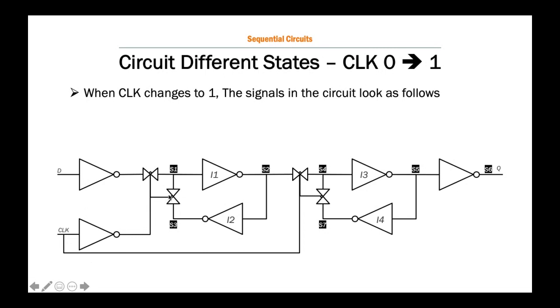So when that happens, the last value that got locked, let's put it this way, is going to be latched. So the last value of D that managed to cross that gate before it closes is going to be latched in here. So now this is in a memory mode, going to continue whatever that value is.